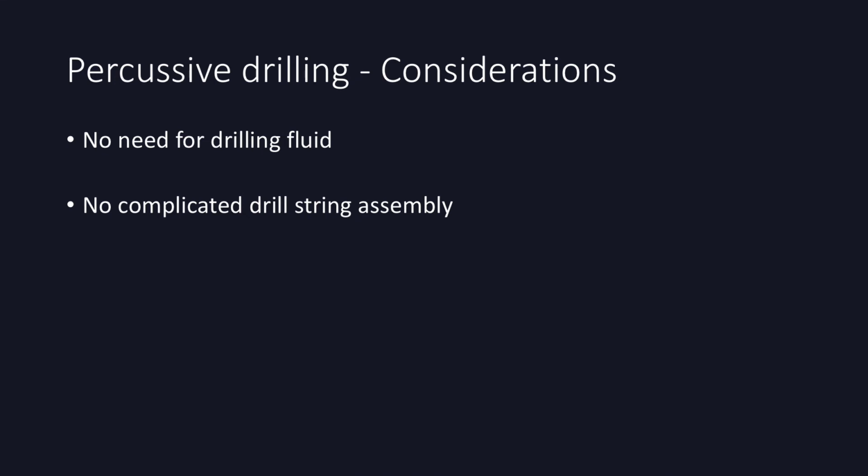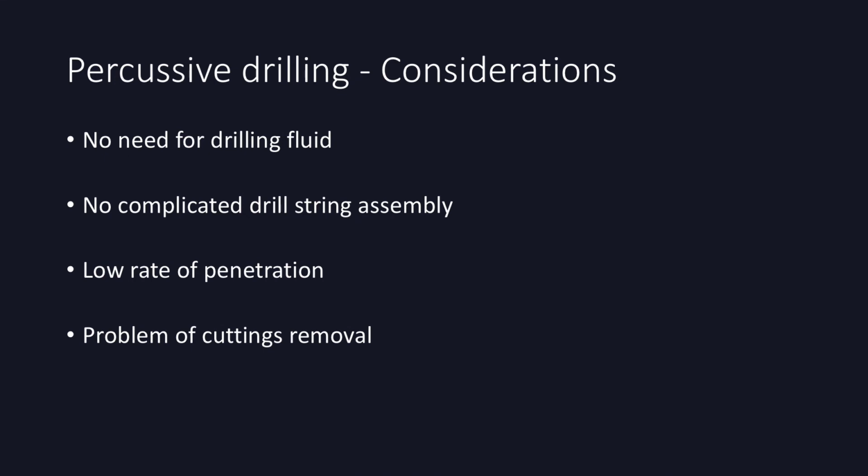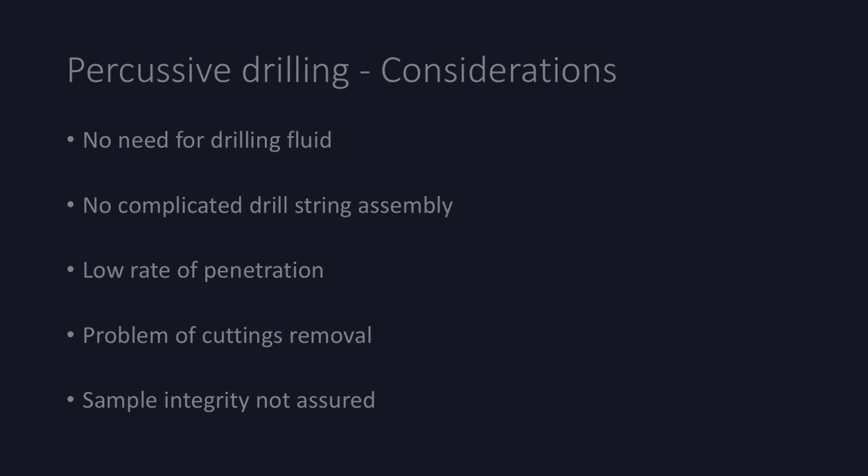On the other hand, this method is associated with a low rate of penetration when it comes to harder rocks. Another problem arises when considering how to transport the chiseled rock out of the borehole. Lastly, core sample integrity is not assured for percussive drilling.